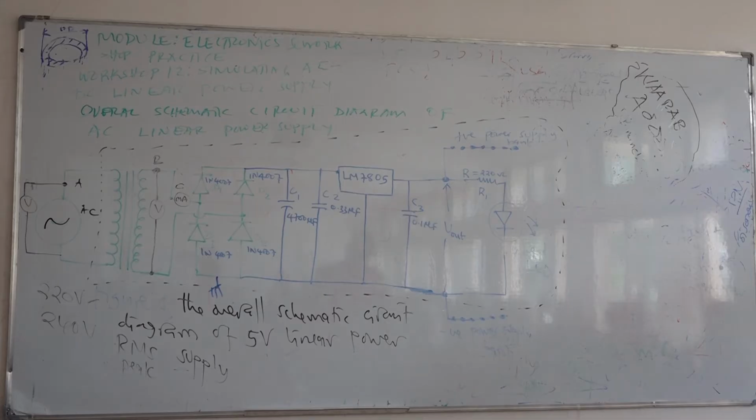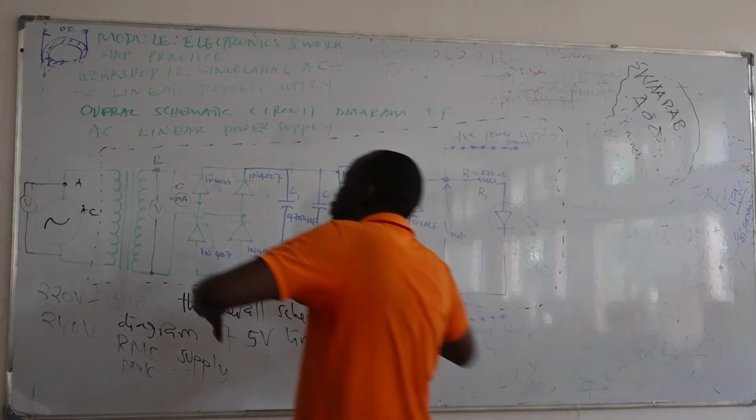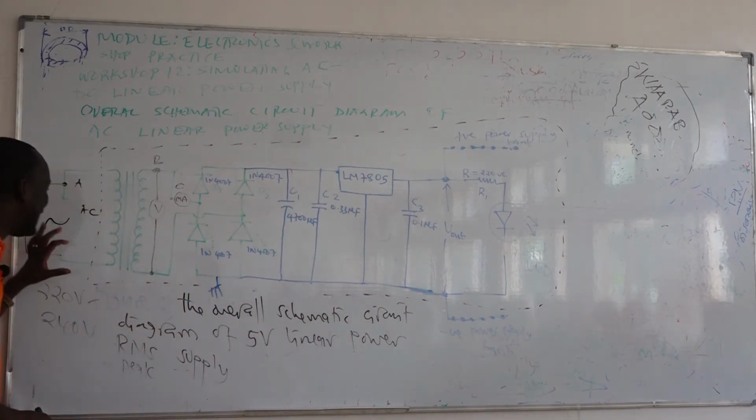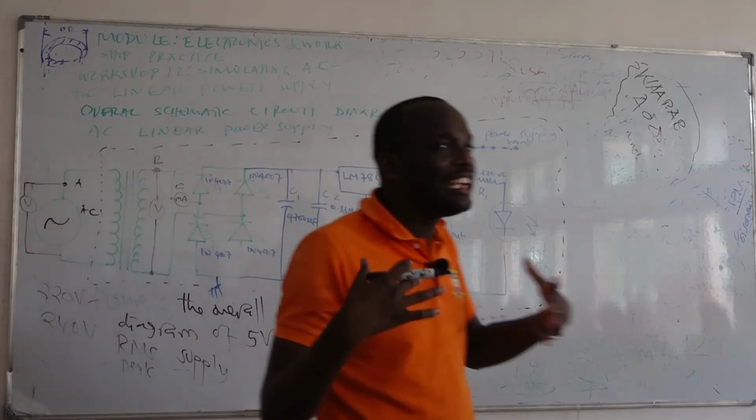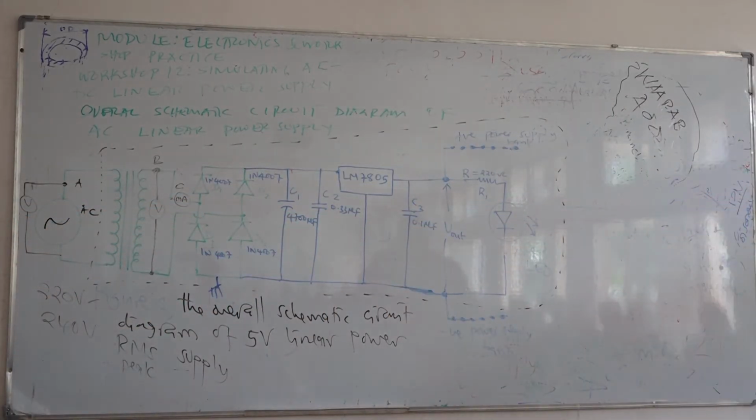Listen. Whenever we have an electronic or electrical system that needs to operate with AC power, and there is no conversion of AC into DC, the important parameter is root mean square voltage and root mean square current. But whenever we want to convert AC into DC, the important parameter is maximum or peak voltage and maximum or peak current.